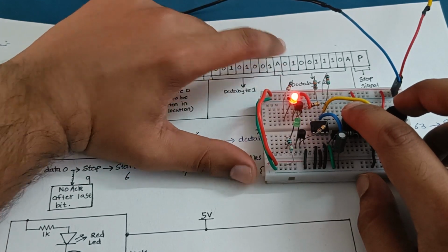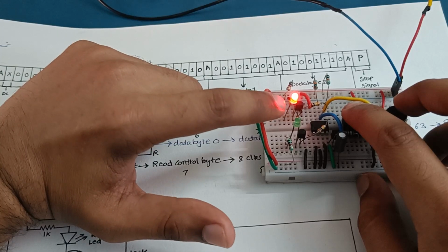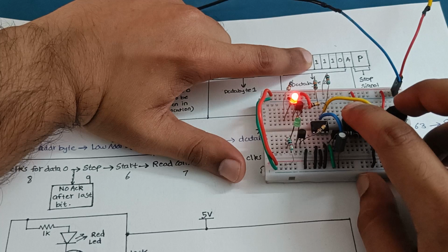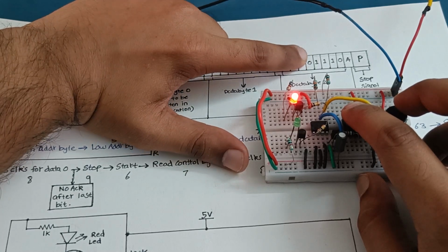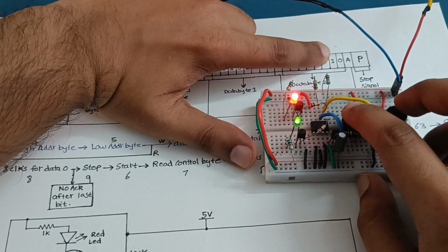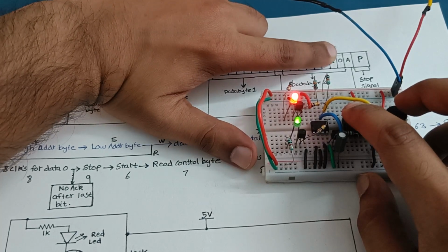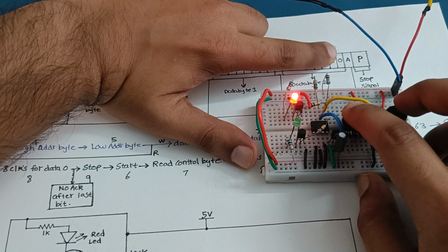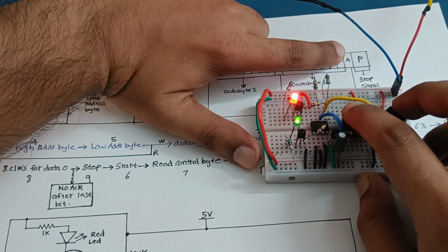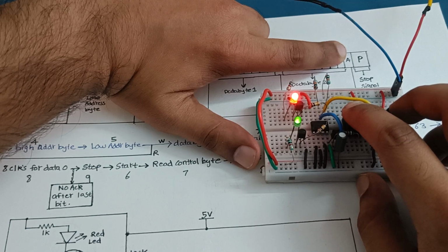So just take a look that on the falling edge we get our data, okay. So on the next falling edge we get a 0, next falling edge 1, next falling edge again 1, next falling edge 1, and this is the last bit, so we get 0. So on the next falling edge put will again become 1, okay.